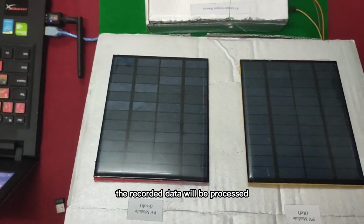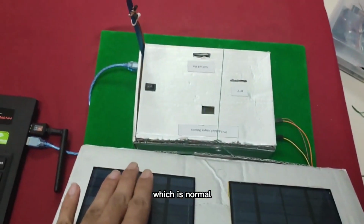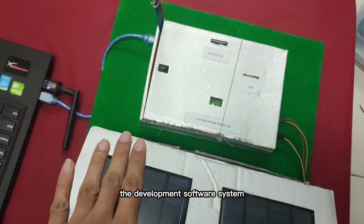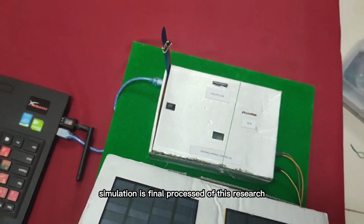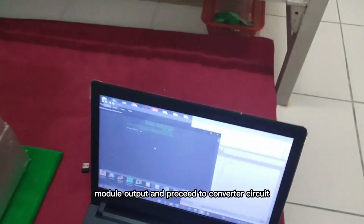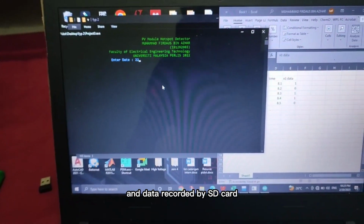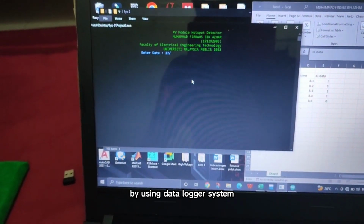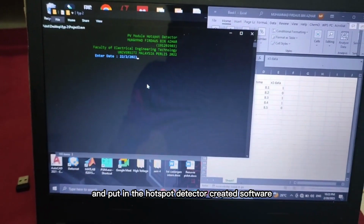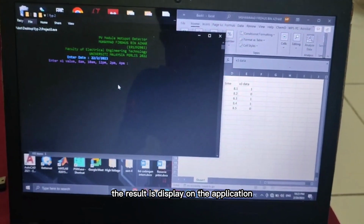The recorded data will be processed in the comparator circuit to analyze the condition of the PV module, which is normal, temporary, and permanent, and display the data on the screen. The software system simulation is the final process of this research. The hardware testing starts from the PV module output and proceeds to the comparator circuit. The output is sent to the Arduino, and data is recorded by an SD card using the data logger system. The data is transferred and rearranged in Excel and put in the hotspot detector software created. As the last phase, the result is displayed on the application.